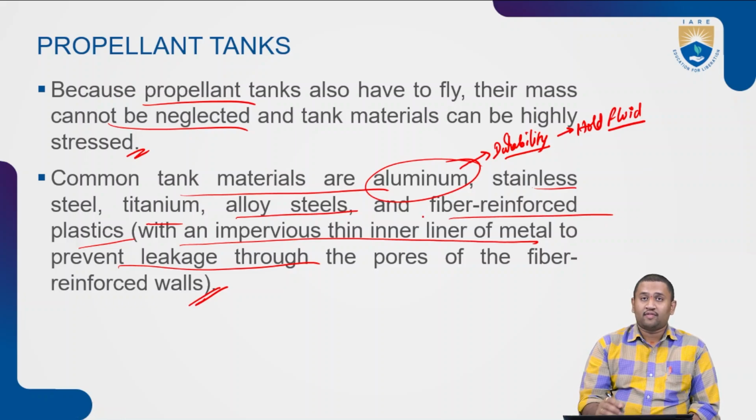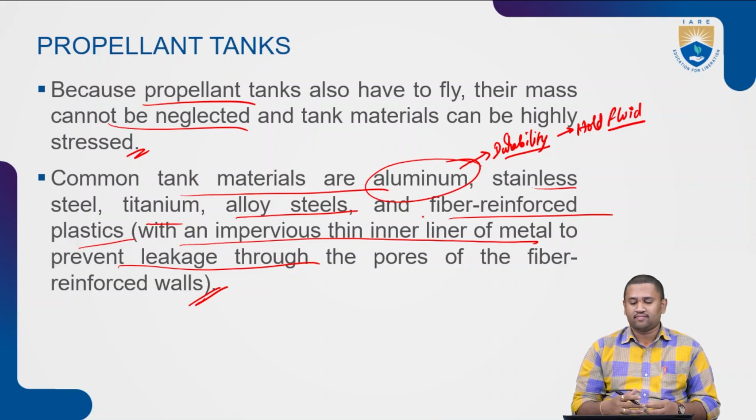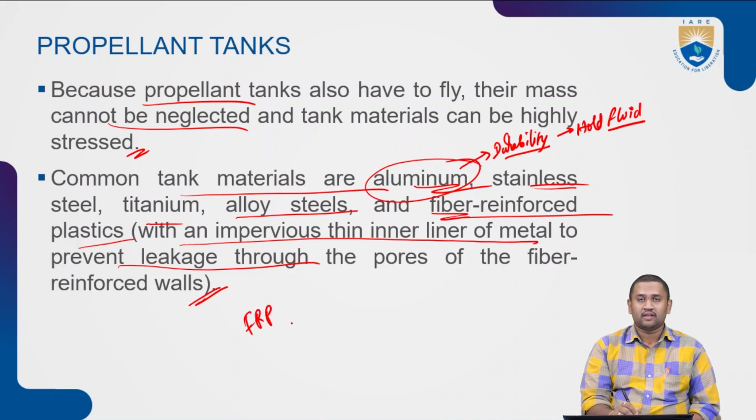Next, as we are creating more, particularly if you are going for cryogenic and others, they tend to have more pressure at ambient temperature or ambient conditions. So in order to withstand that, we can add more material, particularly aluminum or stainless steel, to enhance the structural strength of the tank, or we can change over to fiber reinforced plastics, particularly FRPs, with a coating of a thin metallic layer.